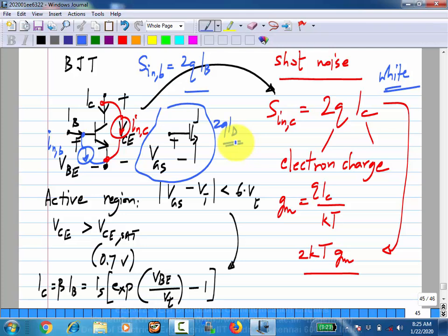So anyway, these are models, and if you have a circuit with bipolar transistors, you can put in the appropriate models and then see. Now these models, just like the small signal models that you would use for small signal equivalents, also depend on small signal parameters like GM, or in this case the total collector current IC.